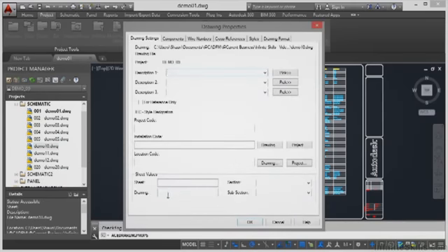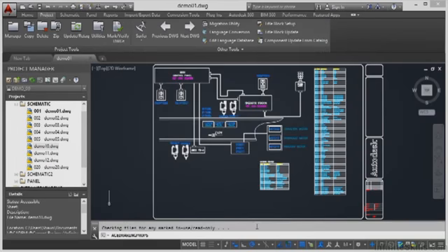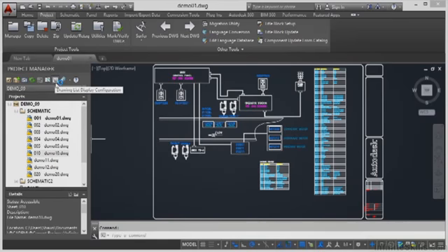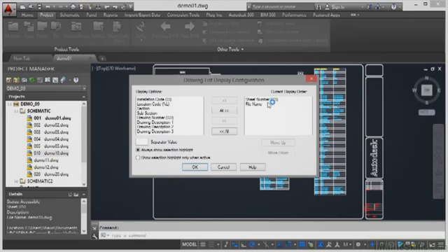Now, there's no sheet number and there's no drawing number. Now, the sheet number for that one is going to be 010 to be consistent with the rest of the drawings in the list. The drawing number, however, is going to be 09 for the project, then an underscore, and then 10 like that. So I'll OK that. Now that'll update, and you'll notice, can you see 010 goes in there? That's because I've changed in here the drawing list display configuration. So we've got sheet number followed by file name.